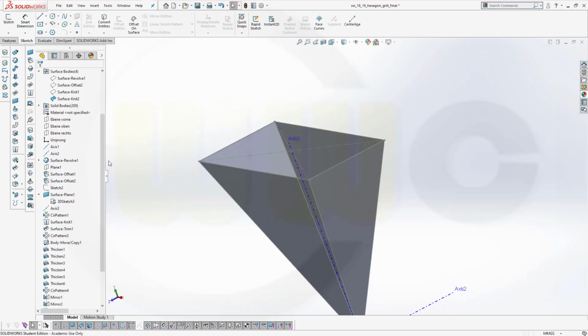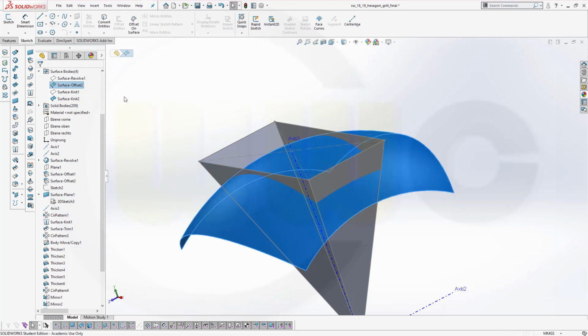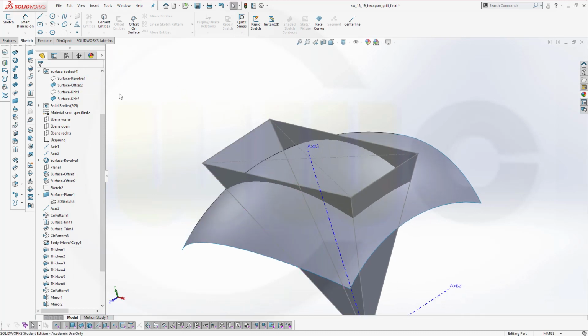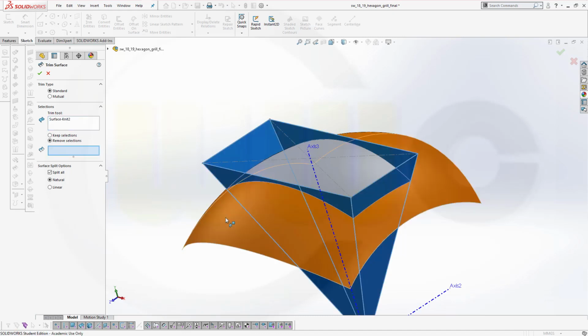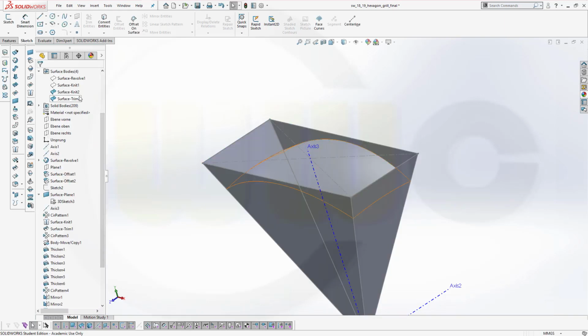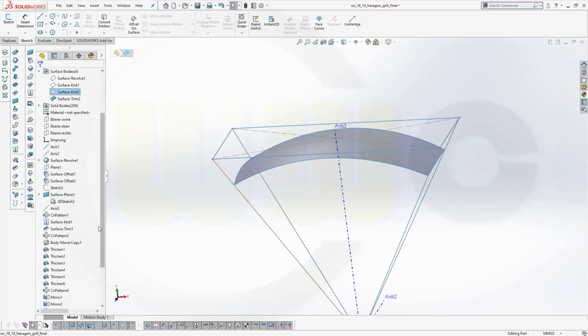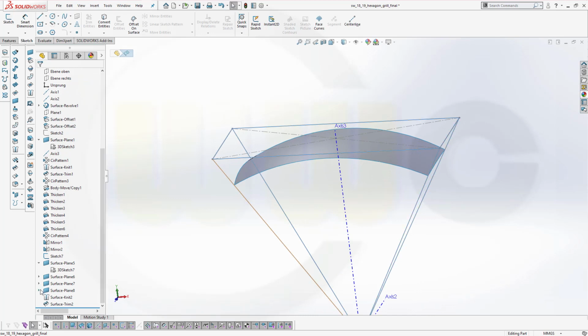Confirm. Now bring back our second surface offset body. That would be this one, I suppose, yes. Now I can trim. So go for trim. The trim tool would be that knitted surface, and I want to remove the outside and confirm. Hide that knitted surface, and now the 3D sketch should be hidden as well. That one is hidden.